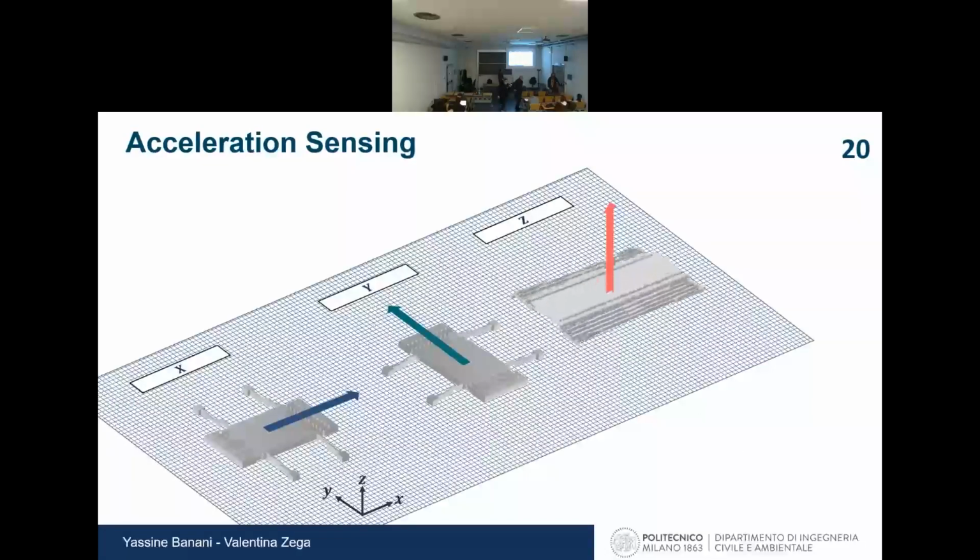And so to answer the first question, yes, we can compute motion without external information, just if we have non-uniform motion, so if you have accelerations. And we have these three devices. These in X and Y, you find in literature; we introduced these things. So the novelty is that with this design, we can also measure Z accelerations with in-plane movement, so in-plane reading.